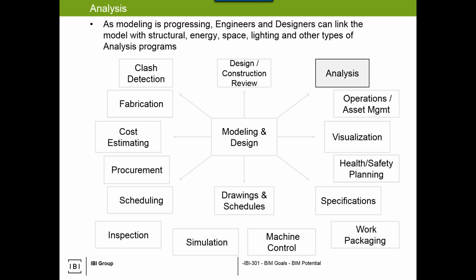Other aspects, using structural analysis as an example, I could take an analytical tool like RAM and a BIM model in Revit, and make the two talk. So if I do a structural analysis in RAM, I can feed that information to Revit, and I could use the member sizes selected in RAM to actually help me populate my model in Revit. Then if I change my member sizes in Revit, I can push back to RAM and update the analytical model and have that bi-directional communication.